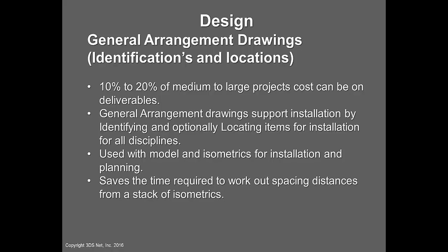Very important for planning. When you're looking at scaffolding to install pipe in the rack, you don't want to work off ISOs and be looking at it one line at a time. You want to be able to put up a scaffold one time and put all the pipes up, that sort of thing. So it saves a lot of time working out spacing distances for pipes in structure